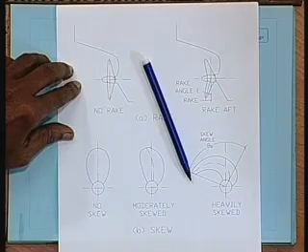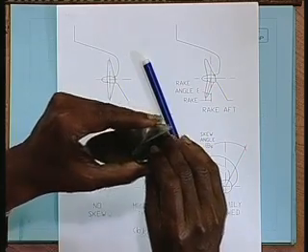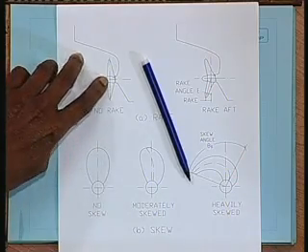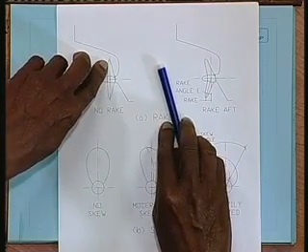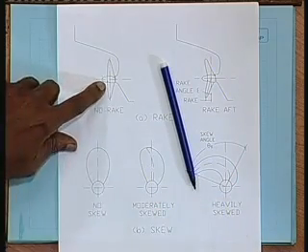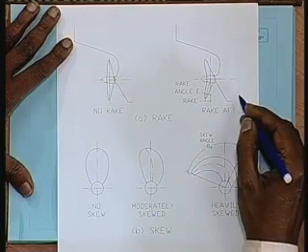If the propeller blade, as in this case, is perpendicular to it in this plane, if it is perpendicular like this, then this is called a propeller with no rake. But sometimes it may be necessary to rake the propeller or tilt the propeller blade to one side of the plane perpendicular to the propeller axis, like it is shown in the next diagram, this diagram.